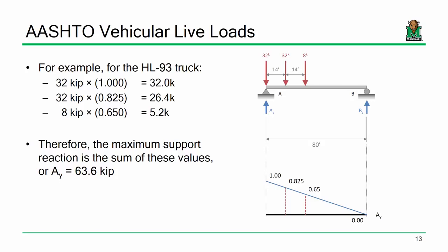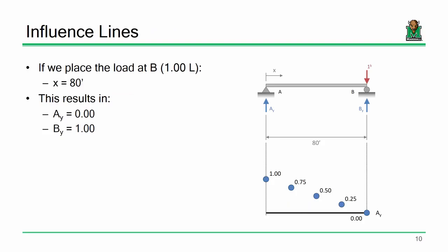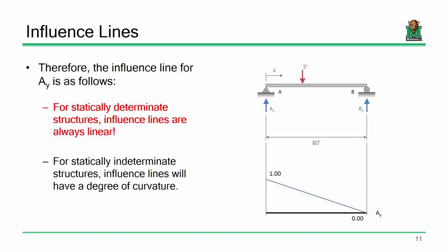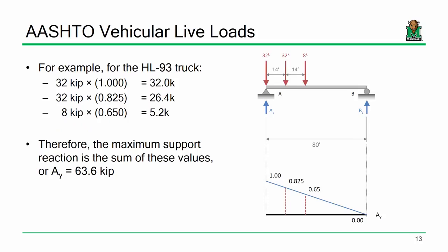Ignore what's going on with the slide, and let's just do a basic example. So let's say I put 20 pounds right smack dab in the middle of this table, 20 pounds. How much goes over here and how much goes over here? 10 pounds. Let's say it's 180 pounds. How much goes here and here? Okay, now how are you doing that? You're just taking it and dividing it by 2, right? I propose what you're doing is you're taking it and multiplying it by the value of the influence line at the center, 0.5. Once you've got the influence line for a point, you can determine the reaction due to any load.